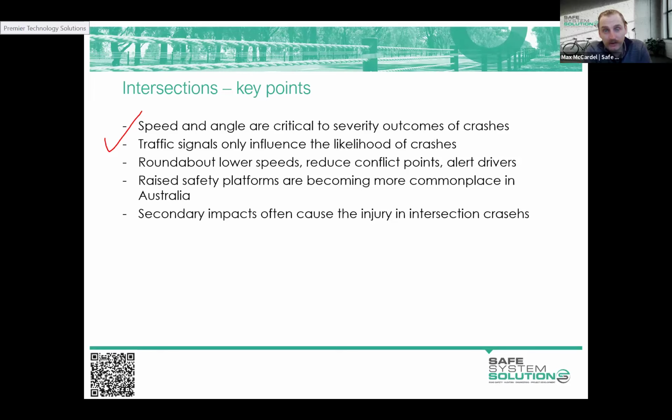So in the scenario where we had the compact roundabout, that was a rural environment and there was no pedestrian demand or anything like that. There were no adjacent footpaths. So those raised platforms, they're not constructed with the idea that they'll be used as crossing points.